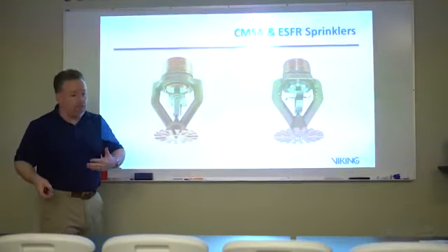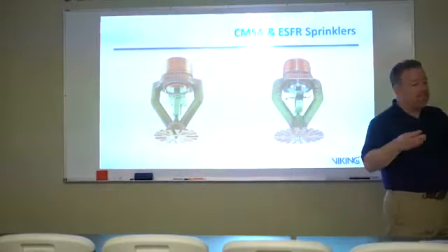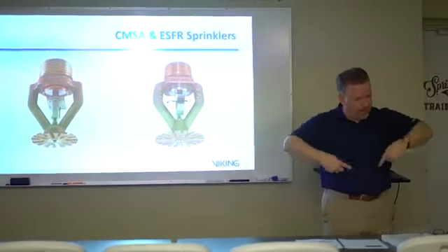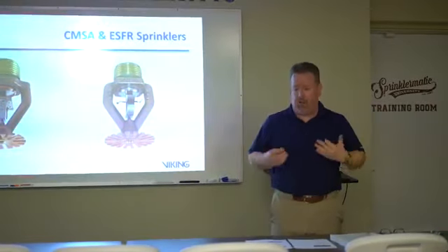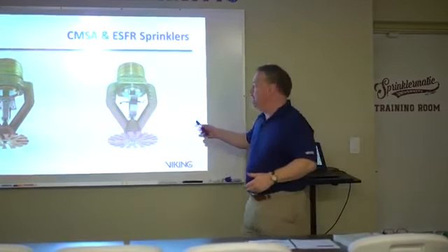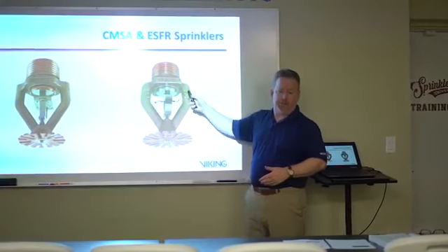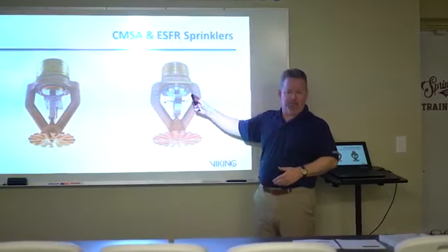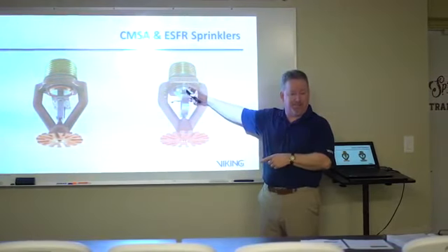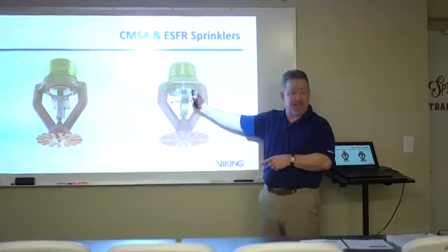Because for 100 years prior to that, sprinkler systems had been designed so that basically they control a fire. You put water on the fire, you wet around the area, and you wait for big water to show up from the fire department to put the fire out. Well, with the development of the ESFR, or Early Suppression Fast Response sprinkler, that changed the game. When you look at the K factors, remember we got down to K 25 and 28, 100 gallons a minute coming out of these?